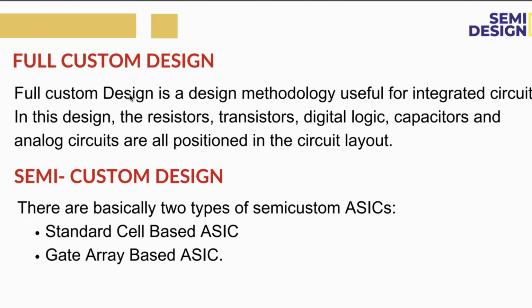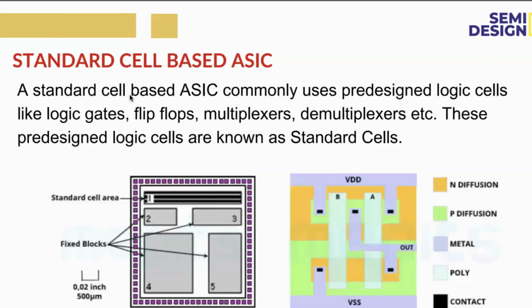Same as SystemVerilog and UVM. Semi-custom design also has two other types: one is standard cell based ASIC and the other is gate array based ASIC. So we'll see what is meant by standard cell and gate array. Standard cell is also predefined, classified under semi-custom. It will have different types of logic gates, flip-flops, multiplexers, demultiplexers, all. So these predefined cells are known as the standard cells.